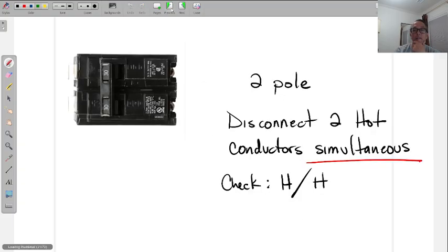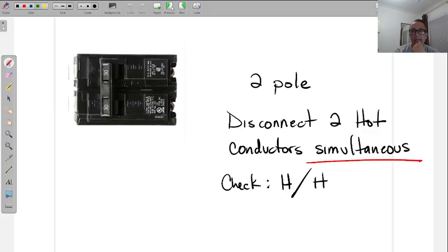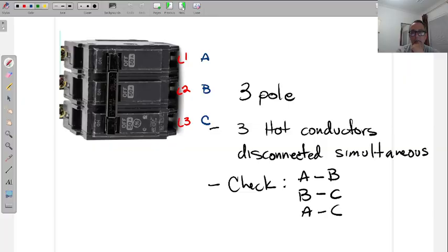All right, so these are the three breakers, no other ones, no fourth. So a single pole, again, single pole, very small breaker. It's only for these lower amperages. And these are for individual circuits. If you need two phases, you don't use two singles. Same as you need three phases, you don't use three singles. And here you just check hot to hot, make sure you have your 240 or 208 or 480. And then three phase, you have to check it 3 times now. Don't just give up after you've checked 2 phases, check all 3. It's good practice to do it that way.